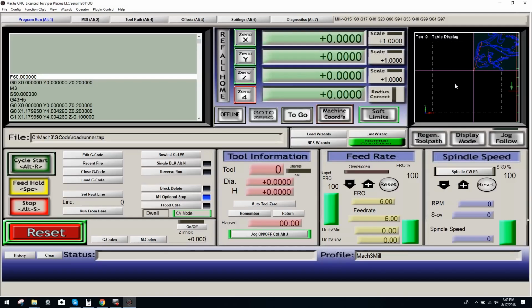Right now, you can see where we are. If once again you jog over, and I've said this many times, but there are some questions that I get. If you jog out of position and want to get back to home position, the only button you need to worry about is 0. Now what we're going to do is go back to G54. We are currently once again in G55. We moved everything over. You can see now you're representing +6 away again because we are still in G55.